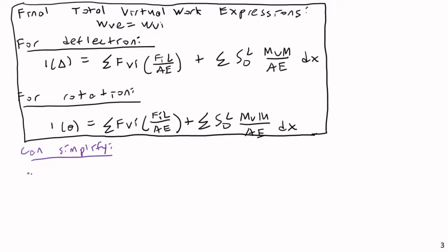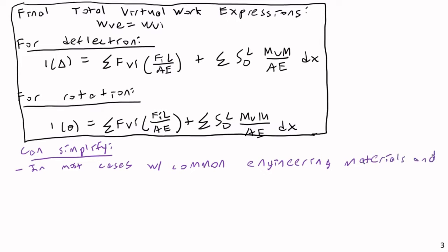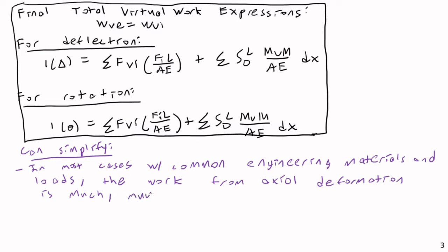And the reason for this is, in most cases, outside of trusses, with common engineering materials and loads, the work from axial forces or axial deformation is much less than the work from bending.